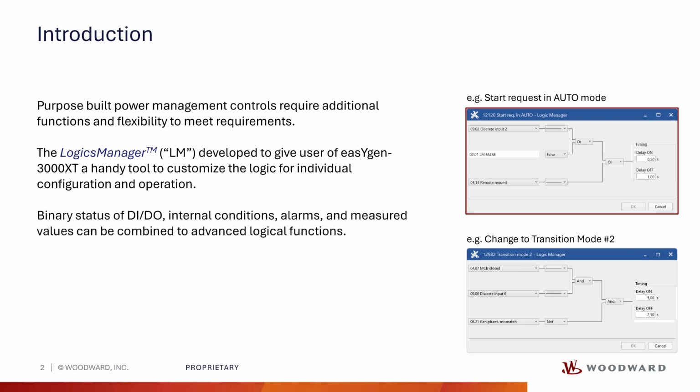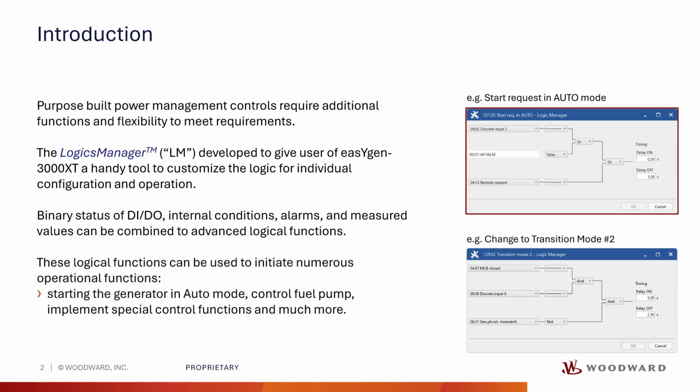The binary status of discrete inputs, discrete outputs, internal conditions, alarms, and measured values can be combined to advanced logical functions. These logical functions can be used to initiate numerous operational functions, such as starting the generator in operation mode auto, to control operation of a fuel pump, to implement special control functions to the present application, and much more.